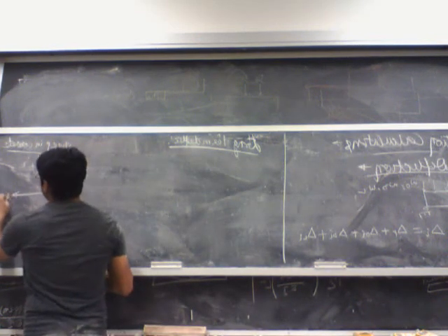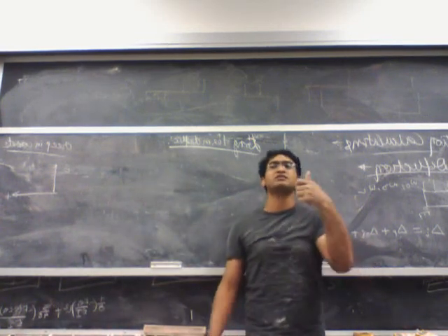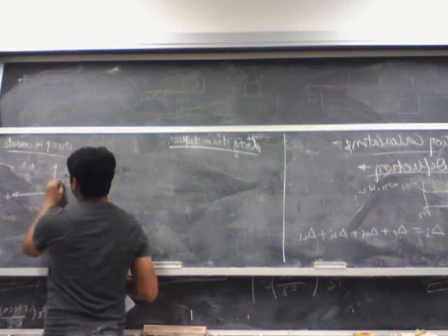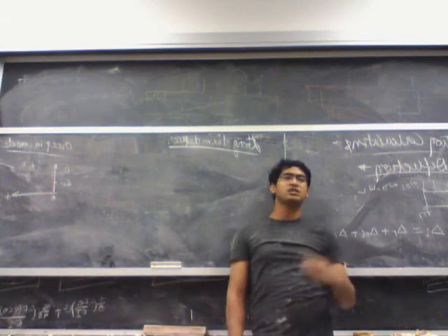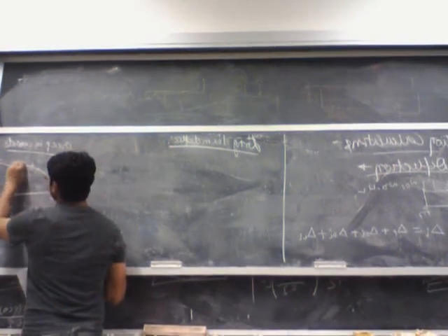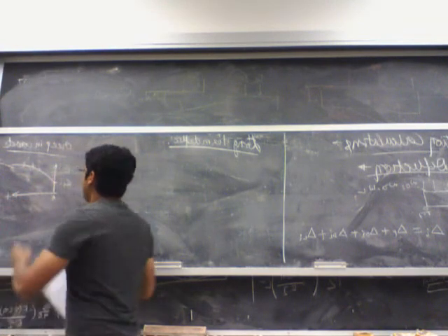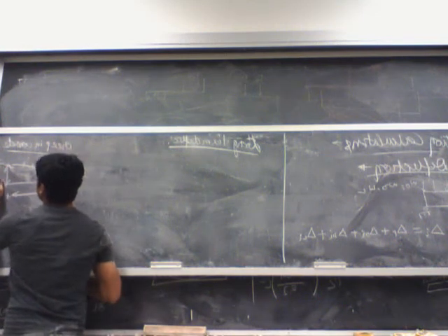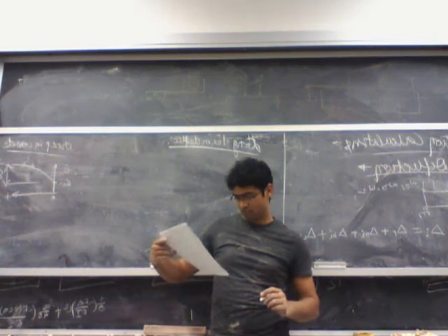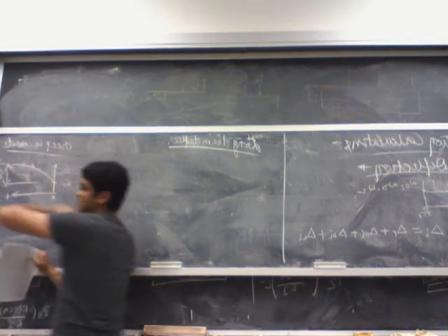If I draw time and, let's say, the strain value, as soon as you apply the load you get some instantaneous strain. Let's say this is the time of load application. So I get epsilon Ci, which is just due to the load applied. And even if I keep the load constant, this strain will keep on increasing until it plateaus off after a very long time. This increase is due to creep, epsilon Cr. Actually, this is epsilon Cru because this is the ultimate, the maximum.